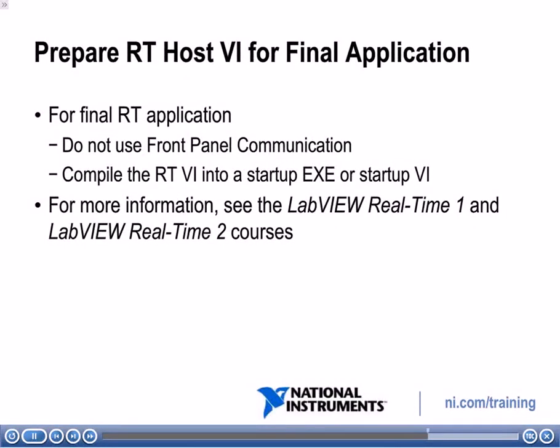When you're done creating and testing your RT host VI, you need to prepare it for your final application. For the final RT application, you don't want to use the front panel communication that we use for debugging and getting started. Instead, we want to compile the RT VI into what's called a startup exe or startup VI. For more information on this, either refer to the help or look at the Real-Time 1 and 2 courses.